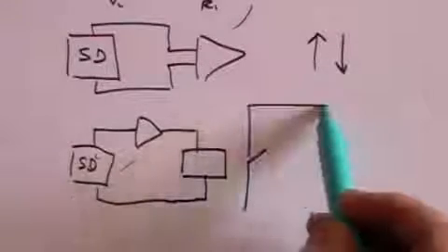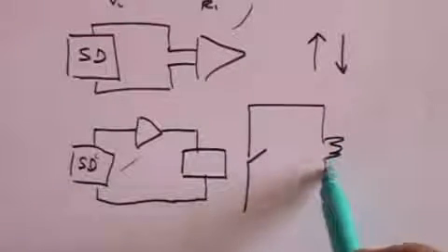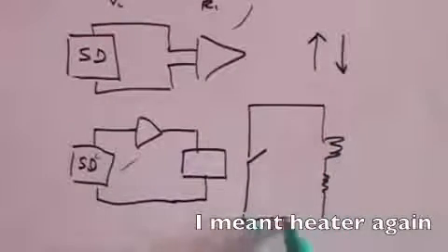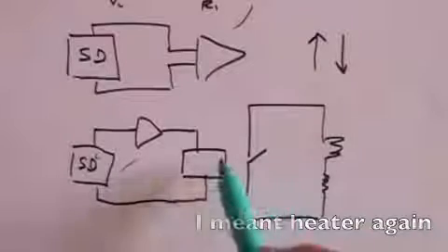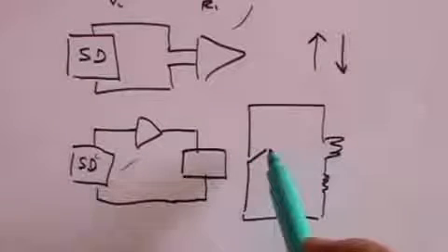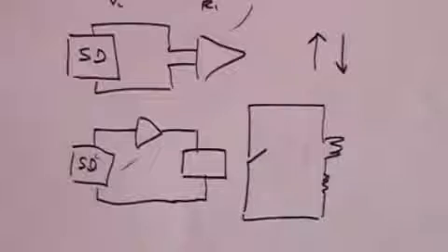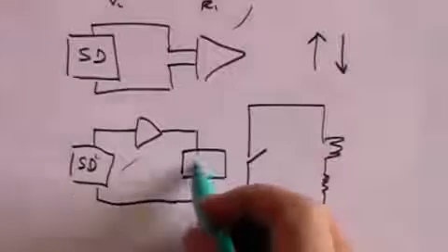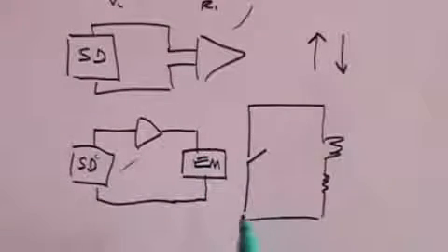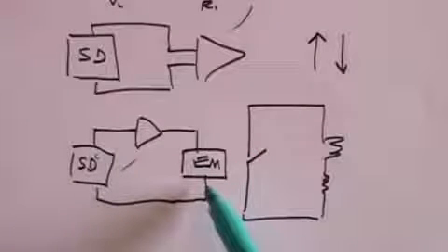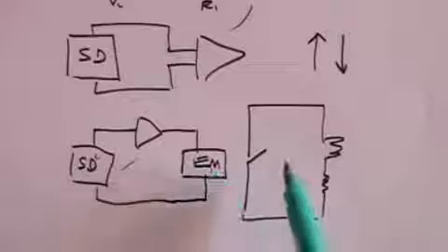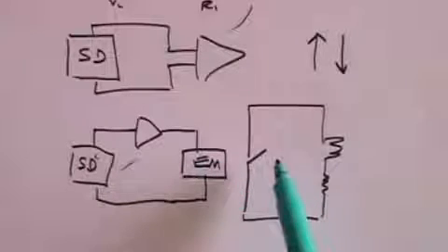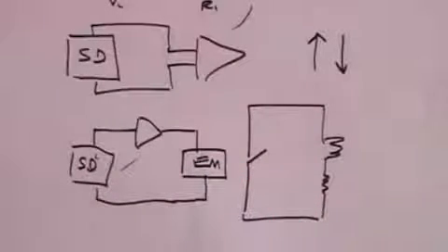And that switch, of course, could then switch on a light or a thermostat or anything you like. And that process whereby a change here causes that switch to close is called a relay. And the best thing to use for that is an electromagnet, something which will not be magnetised until a current flows through it. But when a current flows, this becomes magnetised and causes the switch to close.